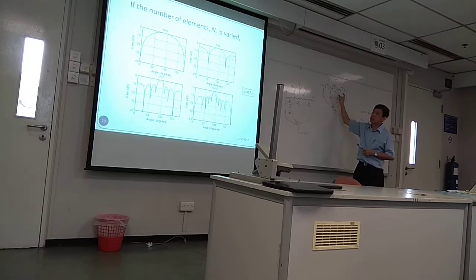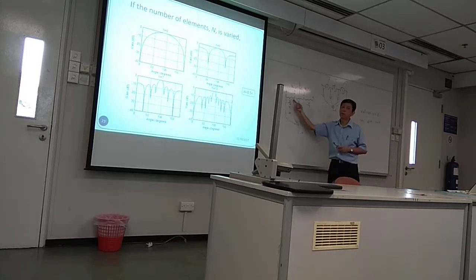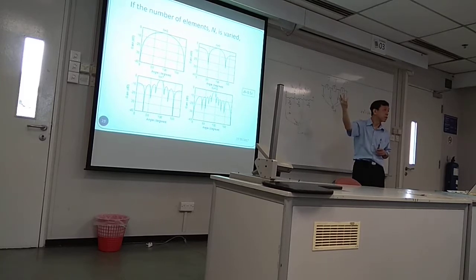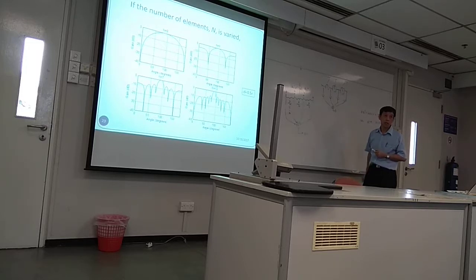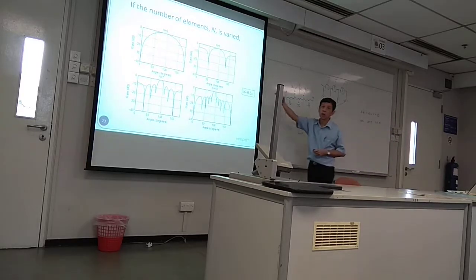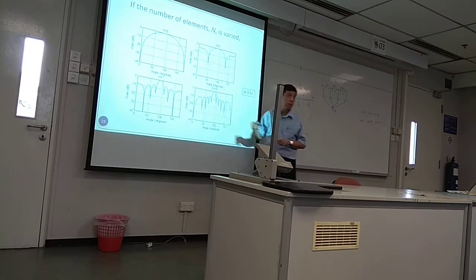You follow? This sampling interval corresponds to the time of propagation through this half wavelength distance. Half wavelength is a 180 degree phase shift. If this sampling interval corresponds to your Nyquist sampling rate, then this corresponds to your 180 degree phase shift. So exactly the same thing. And in this case, the filter coefficients should be all 1 for the case of your uniform linear array.